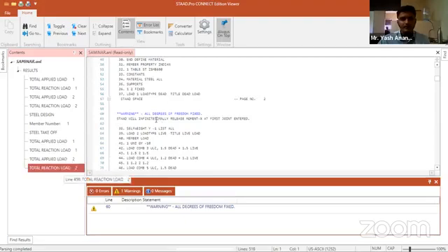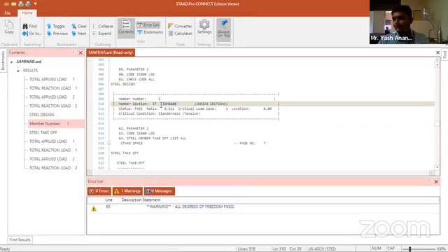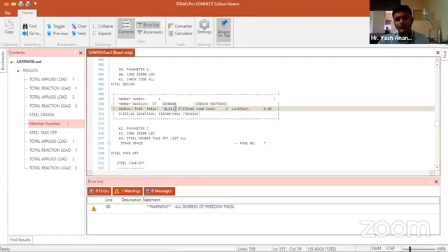In steel design, we are going to see steel design member number one. The member section is passed, taking the load applied. Understand? If a member can take a load of 1 kilonewton and we applied a load of 1 kilonewton, it means its ratio is 1. But here the ratio is 0.66, 0.611. What does it mean? There is 40% more capacity of this section to take load.